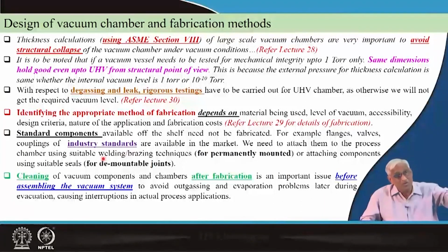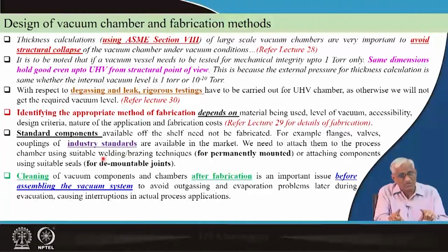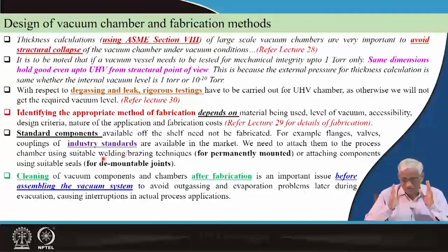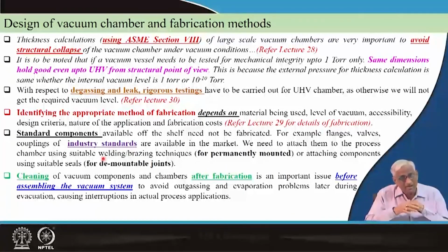Again, you have to have some pumps for only purging, some sources, leak gases. That wall should be UHV compatible. Anything coming into contact with the UHV chamber from the outside world has to cross the barrier of the vacuum chamber. There you have to be careful about seals and materials, components, tightening, torque to be applied, how much torque.